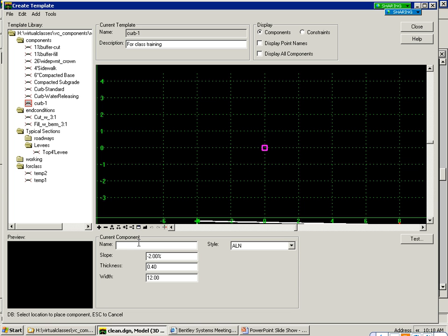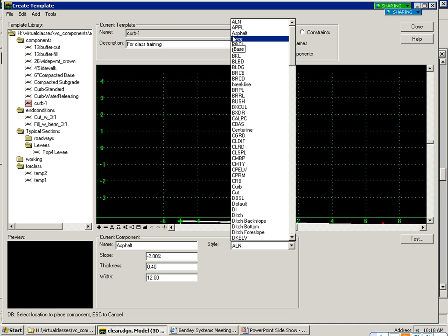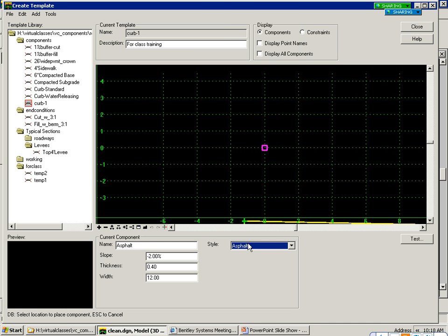So this right here we could just label or name asphalt. Now this name right here, it's important to note, comes through in your volumetrics. So when we do run the roadway designer and a component was named asphalt, or any subsequent components also that were named asphalt, this information will come forward. So here's asphalt, and generally you're going to want to put a feature that matches that.